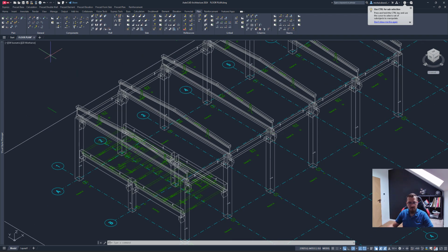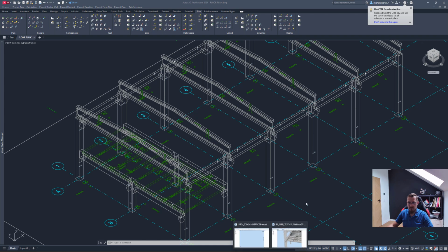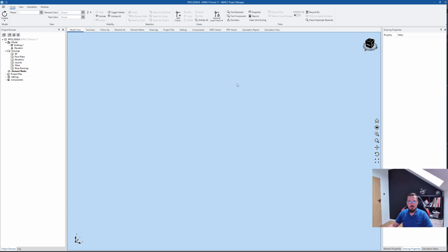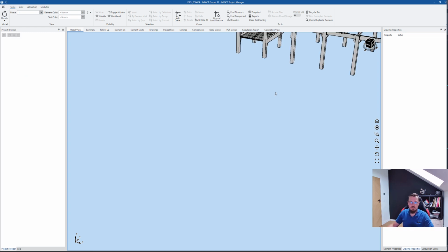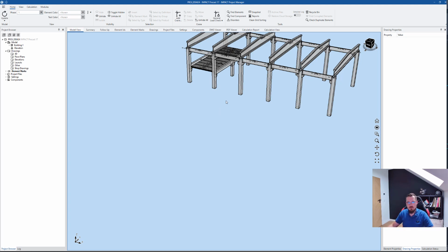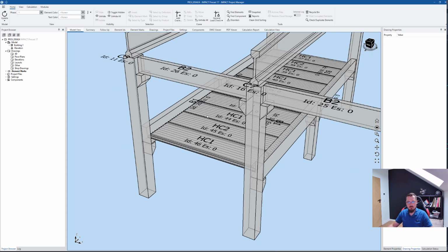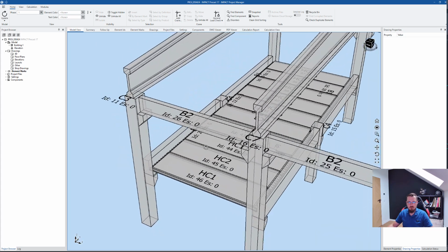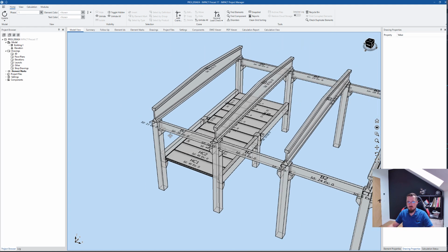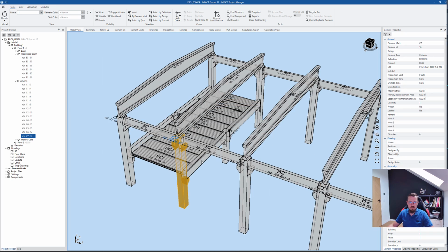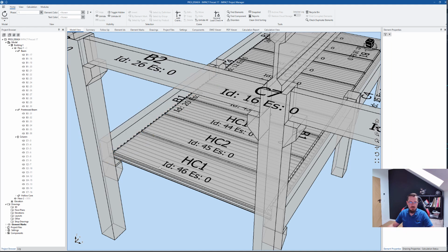With everything being saved, I can go ahead to Project Manager, and that's this one for my project now. I just need to refresh, or rather update, the model. So the database updates with all the elements that we've created, and like so, it loads up the elements. Those are all the beams, columns, and hollow core slabs that we've created. You can see we have the ledged elements, the columns with corbels, the ledged beams as well, and we also have hollow core slabs.